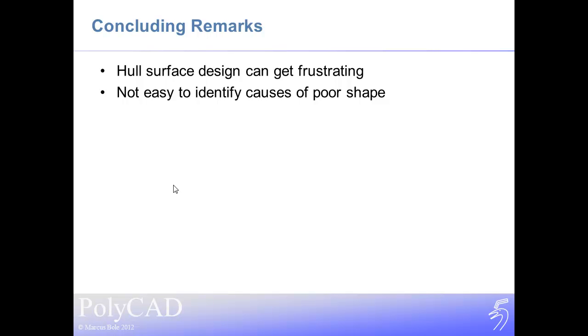We can't really have a system where X marks the spot and there is some system that tells us how to correct it. Fairing tools allow us to smooth the surface, but if, for example, there's a mistake in the parameterization, or there is some connection or some topological reason why the surface cannot be produced in exactly a smooth way, fairing is not going to give us the ability to move or improve the surface. We can move the points around all day, but we might continue to have a problem.